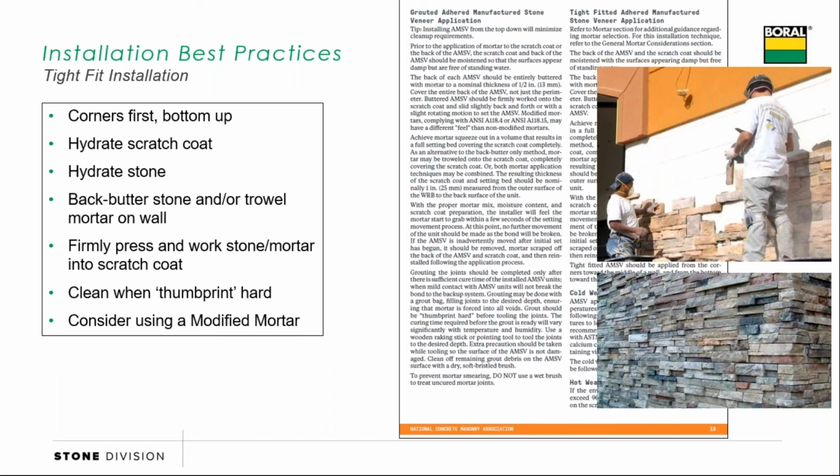We have seen probably a few more warranty claims on tight fit installations than grouted. The reason is they don't have the benefit of the grout joint around all four sides to help hold the stone on. And so if there is a mortar or application issue with a tight fit application, they show up a little bit quicker. And I can tell you that two causes for stones popping off are sometimes mortar that gets mixed too quickly. Mortar manufacturers will tell you to mix for 4 or 5 minutes,